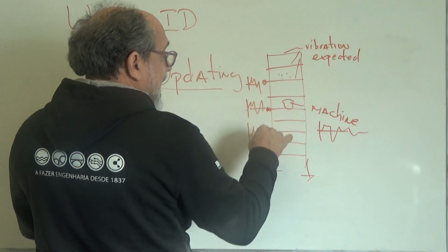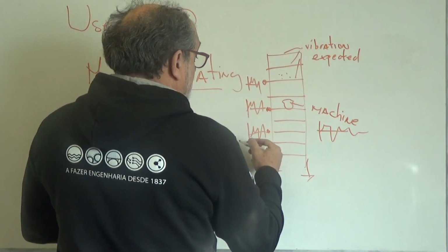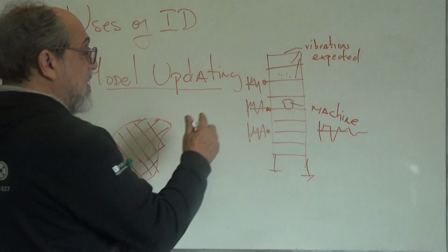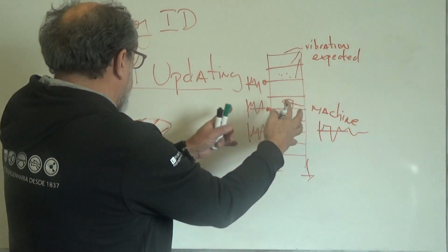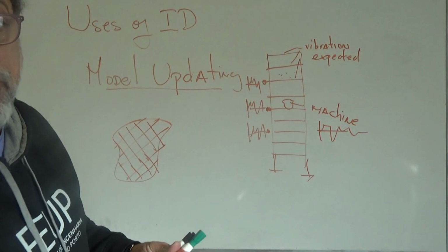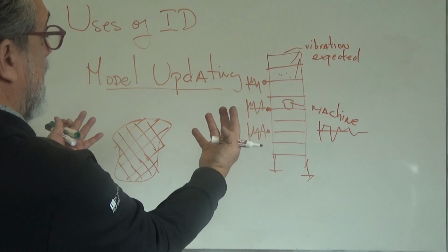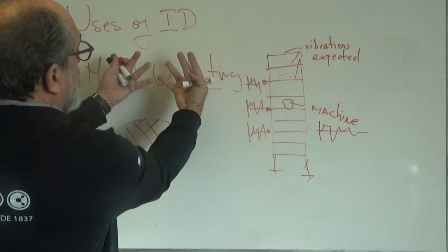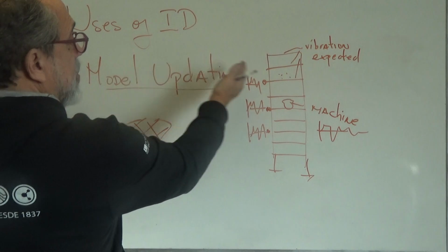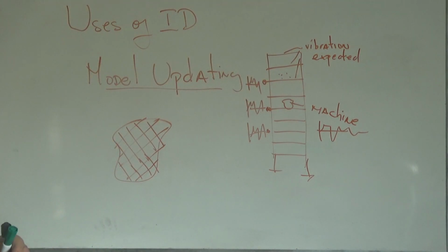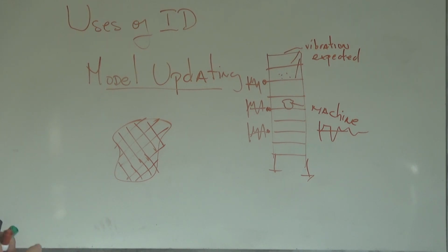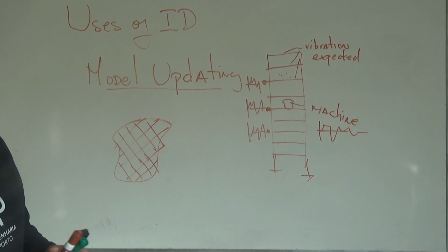And I am going to take that data and say, can I provide some properties of this building from system identification, and then contrast those properties with my finite element model. If my finite element model does not match, and it will not for sure match what I find from the data, then I can try to do something to bring these two things closer together. We refer to that process, of course, as updating the model. Now that's an art, and there's a lot to talk about, and we will actually address it at some point. But that's one application of identification with an existing structure.